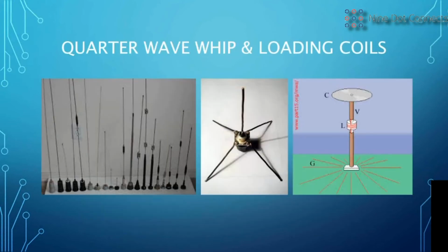So we're not talking about antenna design here. We're talking about PCB design, but you have to understand that if your board is making antennas inadvertently, you're going to have resonances. You're going to have EMI propagating from it. You're probably not going to pass your radiated emissions, and you may not pass your susceptibility testing.